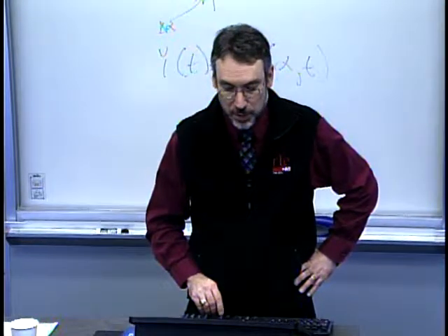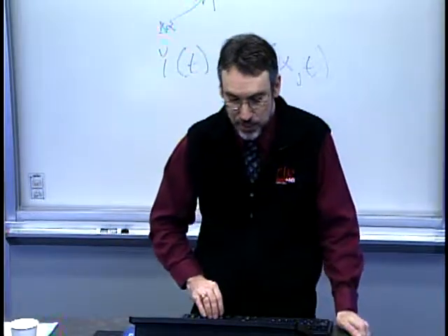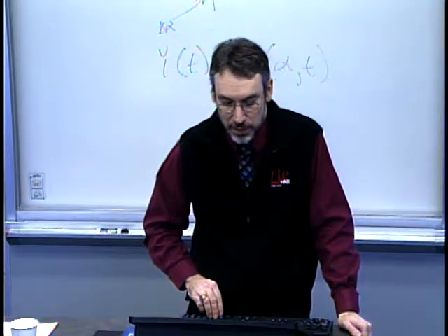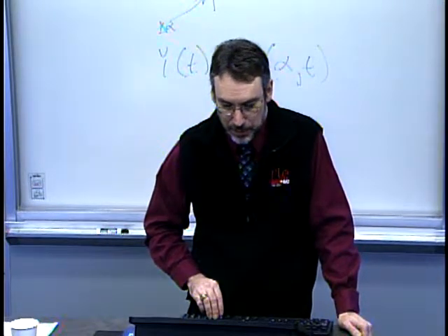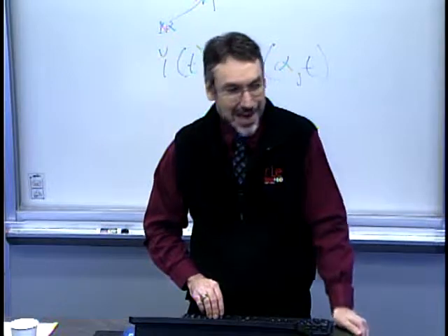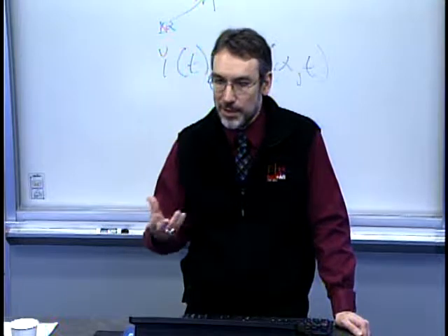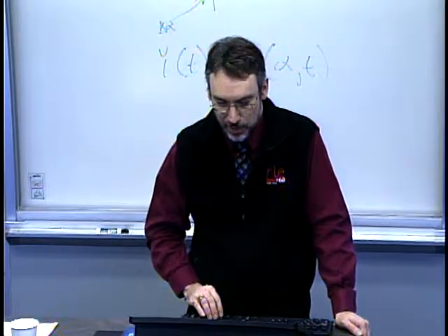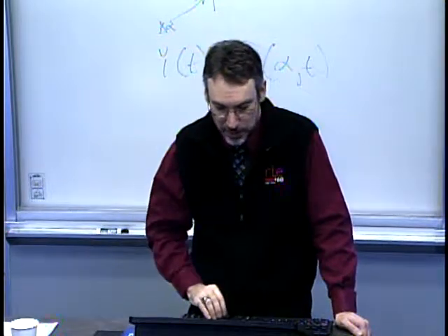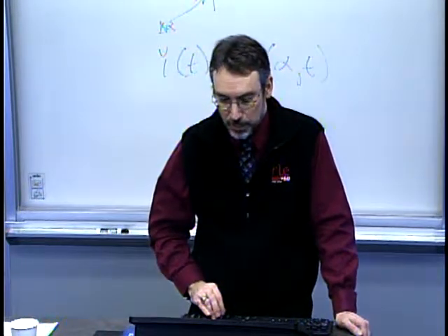Here's another one. This is break bending of a metal sheet. And the basic idea in this process is we're trying to change the geometry under the application of force in a bending process. So we might have some tooling. We have some piece of metal, say, and we press down. And the intent is to create some permanent deformation in the part. An important component here is that when we remove that force, remove that pressure, there can be spring back in that part.